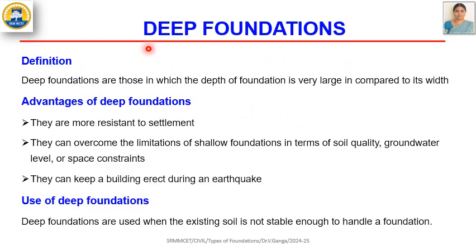Coming to deep foundations, they are defined as foundations where the depth is very large when compared to the width. Some of the advantages of deep foundations are that they have equal settlement. The limitations of shallow foundations are overcome by the use of deep foundations. They also act as earthquake resistant structures. Deep foundations are used when the existing soil is not suitable enough to handle the foundations.